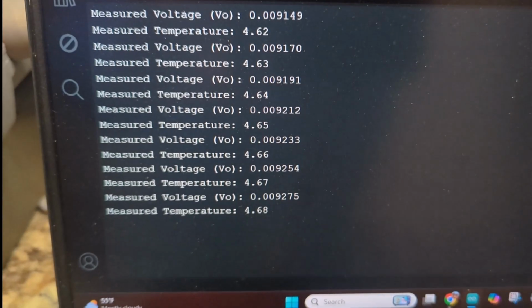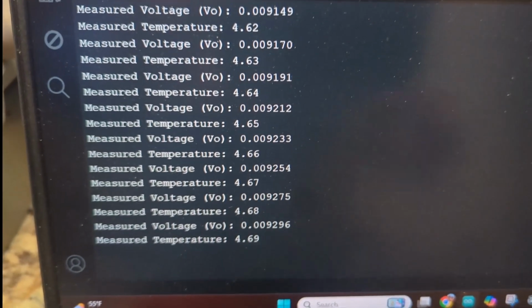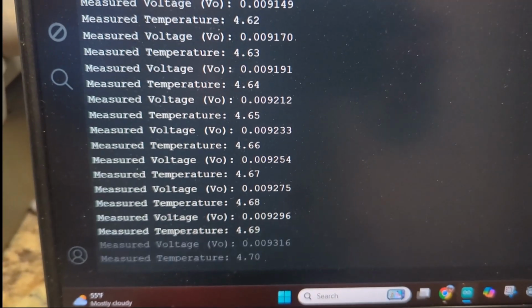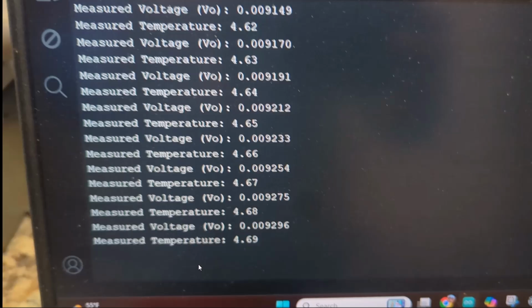And it's doing it very slowly, but it's doing it on a very consistent basis based on the temperature in that room. So the idea is you can see the temperature slowly going up from the water warming up. So not only were we making a very accurate resistance measurement, but we are getting very good consistent resolution because we have very low noise in this measurement.